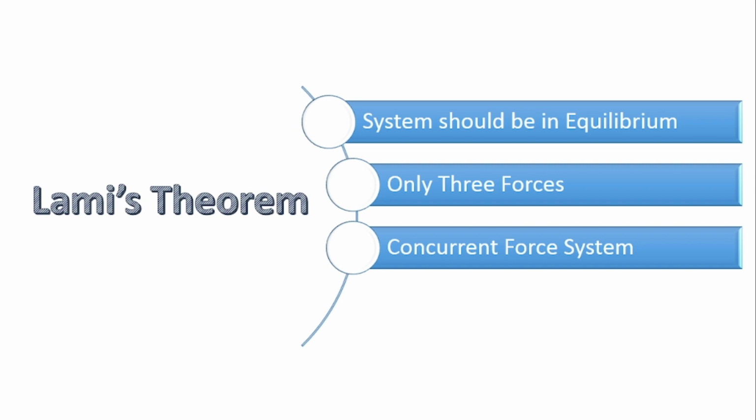The next condition is concurrent force system. Lami's theorem is only applicable for the concurrent force system. So when a system has 3 concurrent forces, then only we can apply Lami's theorem. We cannot apply it for parallel or general force systems.